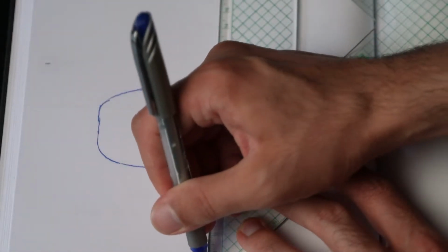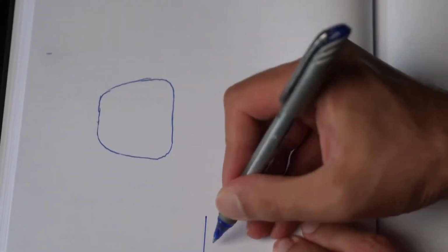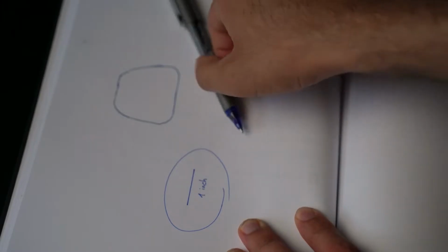If I take that and somehow bring that into SolidWorks via measurement or any other method, then I can take it from there. I can create the inner sides of the pocket, create the walls of the pocket, and so on and so forth. So task number 1 is measuring the circumference of the light. And since in this case, it has a very odd geometry, nothing like a square or circle that I can use my calipers to measure, I would put it on a piece of paper, preferably gridded because it's already scaled, or a normal plane, and draw around its circumference as accurately as possible.